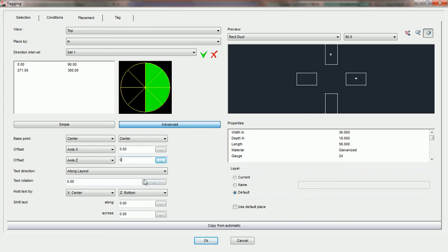In this part of the tutorial for the placement tab, we're going to show you how to utilize formulas to calculate your offset and positioning parameters for you. Thus far, we've taught you how to place the proper offset values into each field dependent upon the automatic you'd like to run. However, you can also have PractiCAD use mathematical formulas or expressions to choose the value of these fields. You will notice next to both offset parameters, the text rotation, and the shift text parameters that there is a little dialog box that you can check.